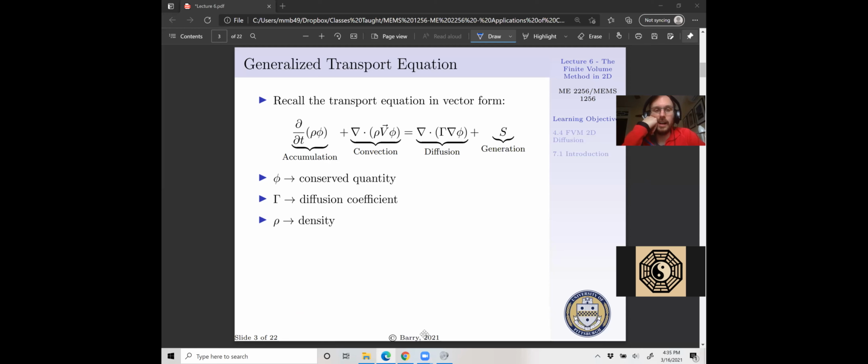All right. Now, we should be pretty familiar with this equation. And right now, we've been neglecting convection because that's going to take a lot. Because within convection, we need to be able to apply this equation and look at the Navier-Stokes equations and recognize that for our problem to be bounded, we typically need velocity specification and pressure specification. And what we see a lot of times is that pressure velocity coupling gets pretty tricky. And for us to be able to solve it directly, i.e. DNS, direct numerical simulation, it becomes computationally prohibitive.